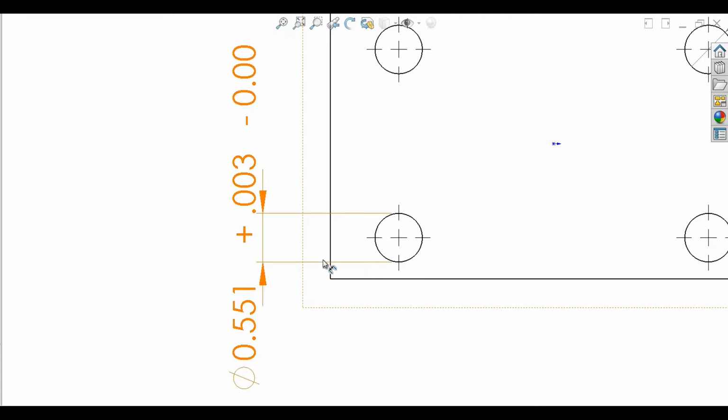But the accuracy of that measurement might be plus or minus 0.002. So while it has a resolution that goes all the way down to 1,000th of an inch, it has an inaccuracy potentially of 2/1,000ths of an inch.